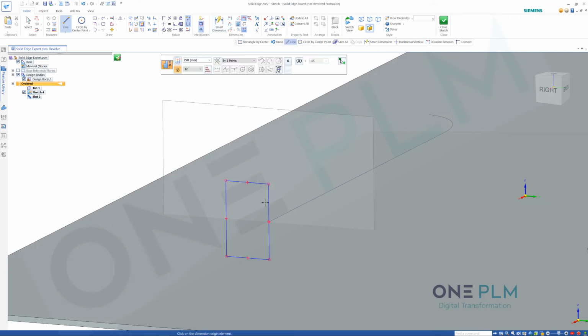I'm going to dimension this up using symmetric diameter. So select the center point and then the outside edge. That's going to give me the overall symmetric size. So that's my 50. The height doesn't matter on this one, but I'm just going to go 20 mil on there.